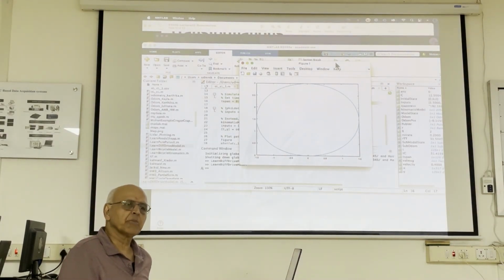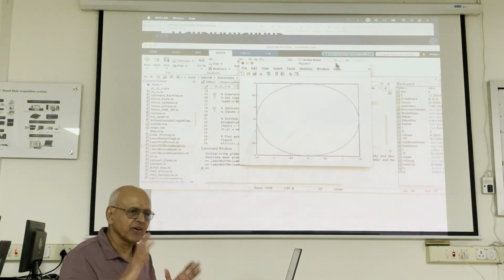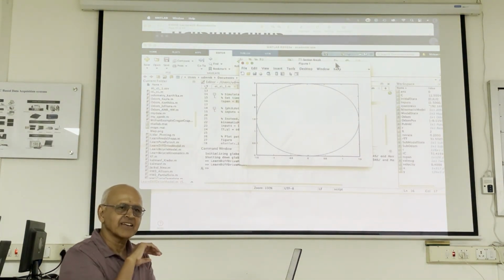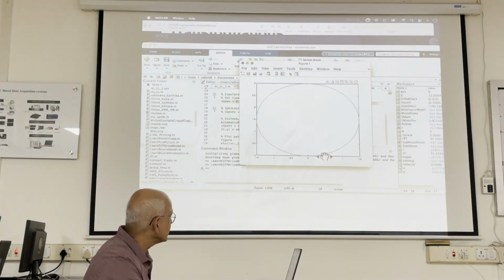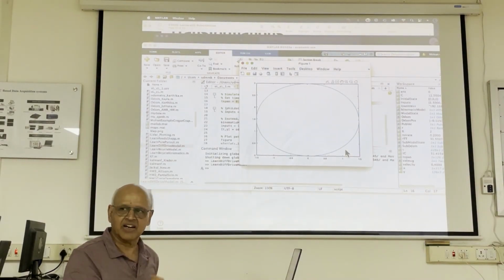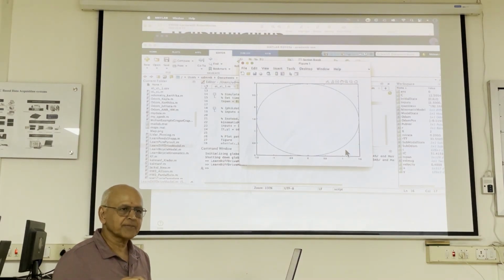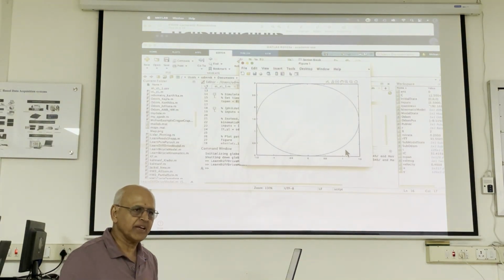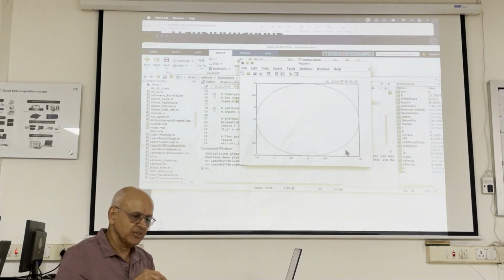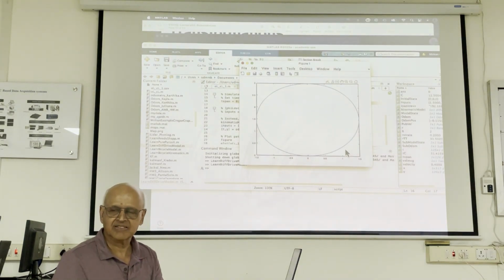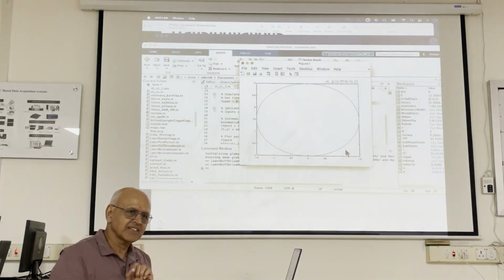So now I'm going to let you think about an exercise over lunch, but maybe don't think about it because you want to relax over lunch. Depends on how good the food is, right? If the food is lousy, then you start thinking. But what if I change the V and omega, instead of letting it go this way? Find a way of running that MATLAB program by giving it an array of values of V and omega. So you can say for 0.2 seconds, use this V and omega. After that, change it to a different V and omega. You should be able to do curved paths of different kinds. So different tiny circles, right?